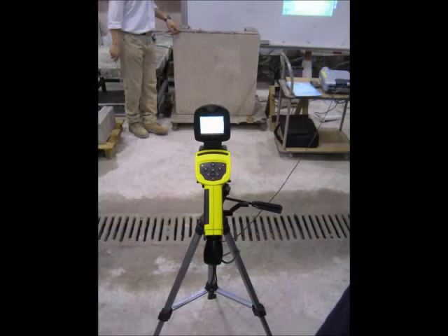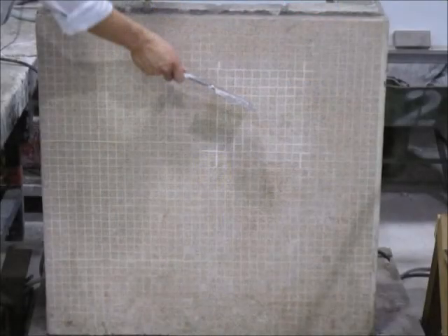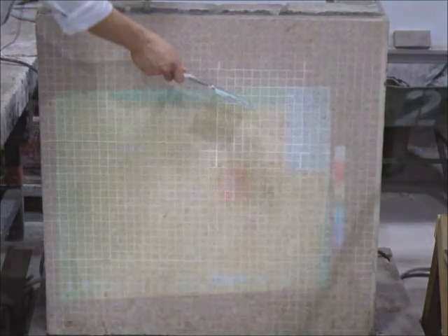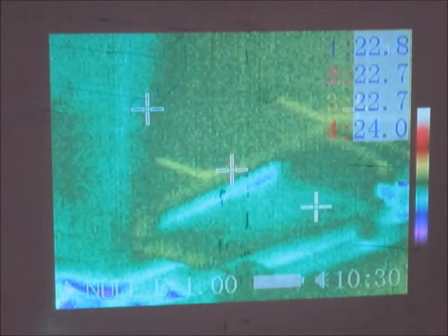The fifth one is the infrared thermographic test. It can be used to identify performance failures, including heat leaks, to improve the efficiency of cooling or heating air conditioning, water pipe leakage detection, and external wall debonding.